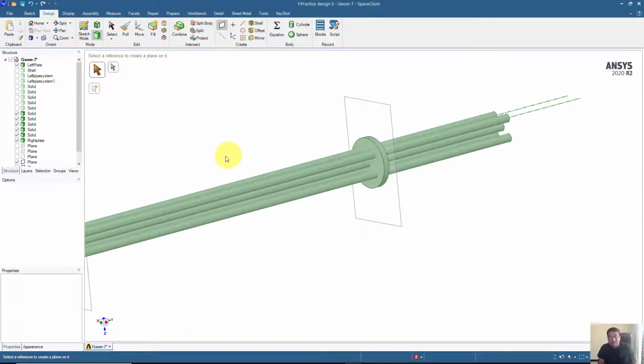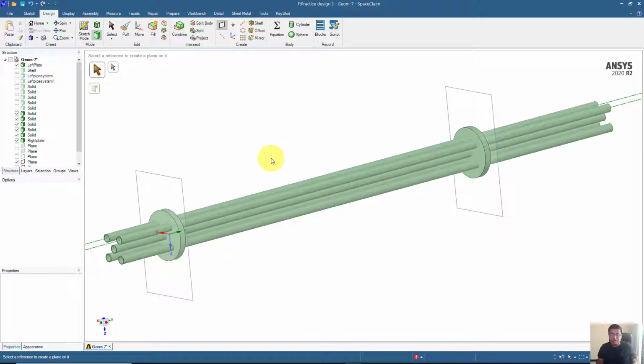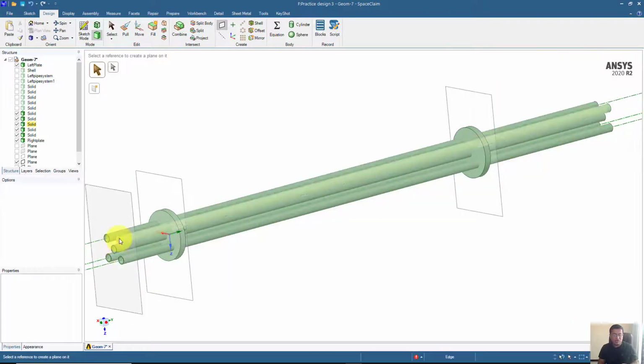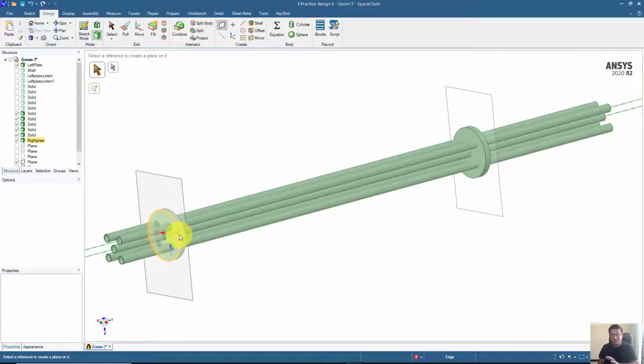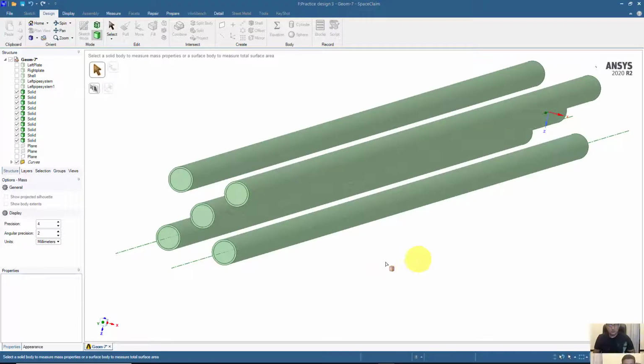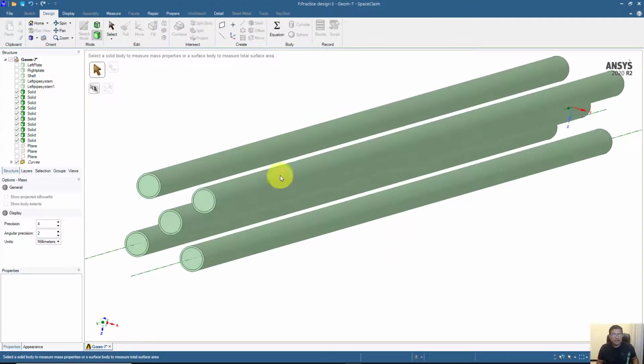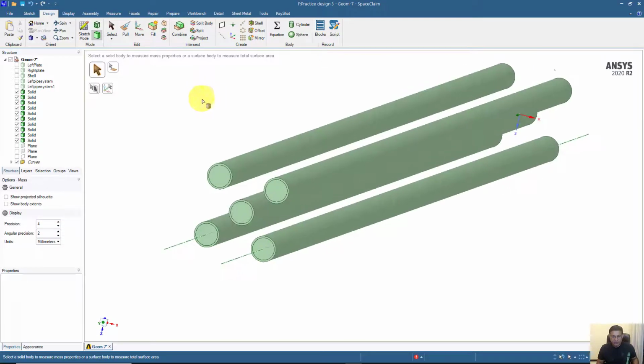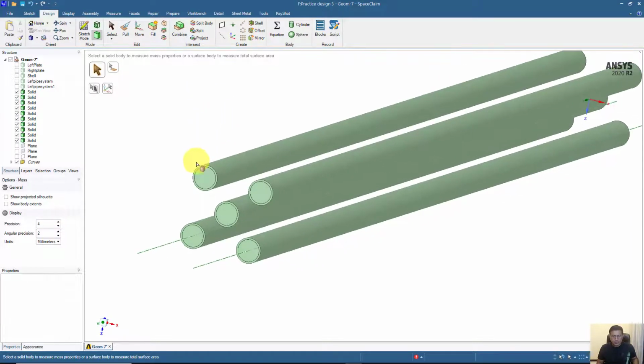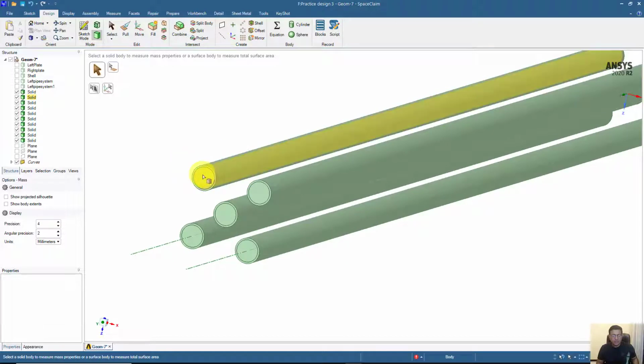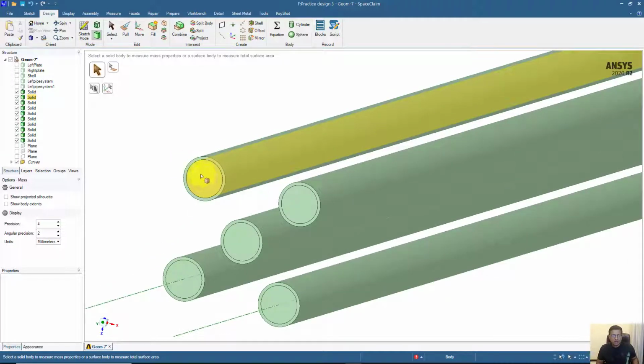And I will repeat the same procedure that we did in the tubes case, and I will remove extra parts from them, and this will not be shown in the video. And after applying the combine command, now you can see that we have these 5 tubes, and also we have thickness of these 5 tubes, and dimensions are 5.8 millimeter for this internal part of the tube, and the thickness has a diameter of 6.7 millimeter.